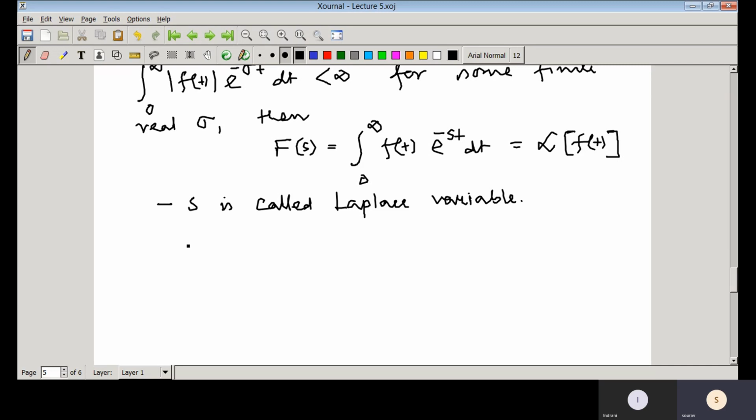So one-sided Laplace transform, it makes sense since the systems are causal, and that integration limit here, you can see that integration limit we have taken, that is that 0. So basically this is 0 minus. The reason is we take 0 minus to handle the jump discontinuity at origin. So in control we will be taking one-sided Laplace transform, and it makes sense since the systems are causal.